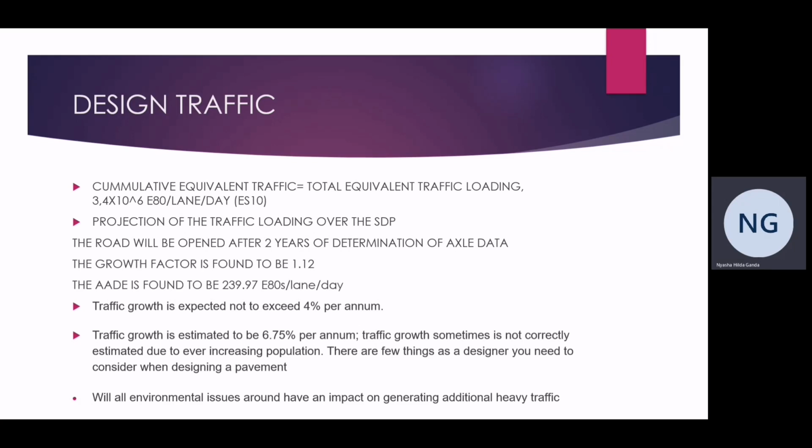Design traffic. The cumulative equivalent traffic is equal to the total equivalent traffic loading. As we calculated in our project, we got 3.4 million E80 per lane per day, which falls under class ES10. Projection of the traffic loading over the SDP.